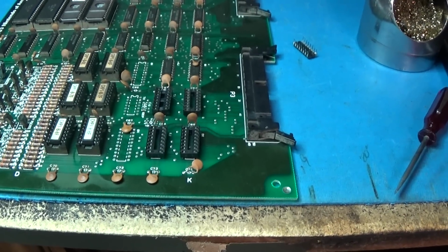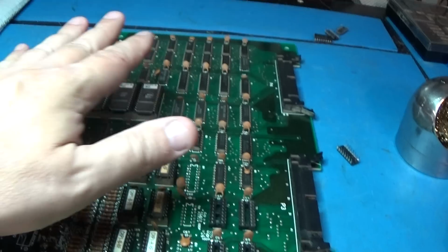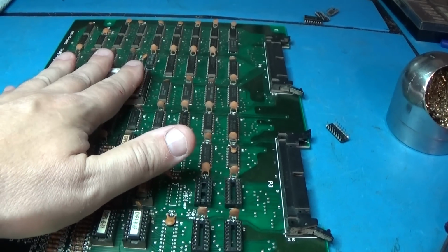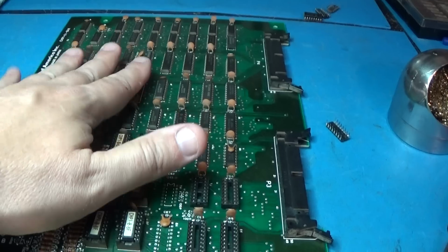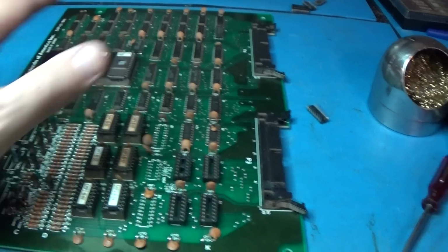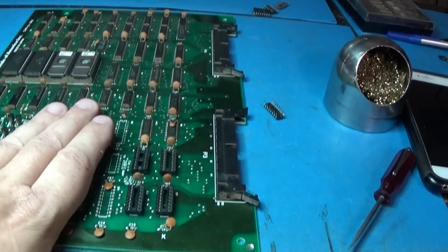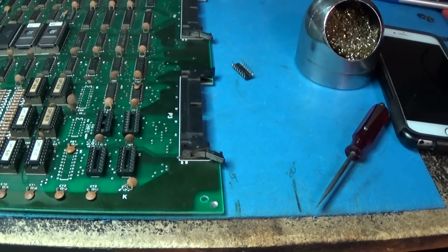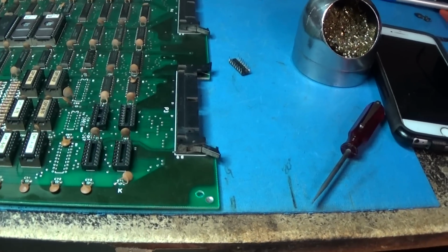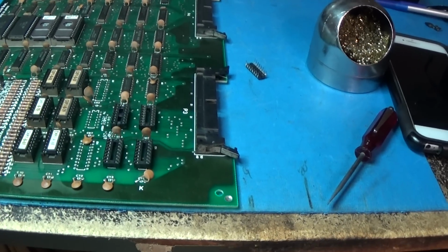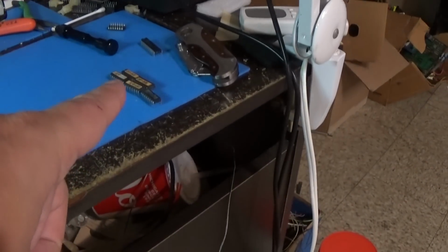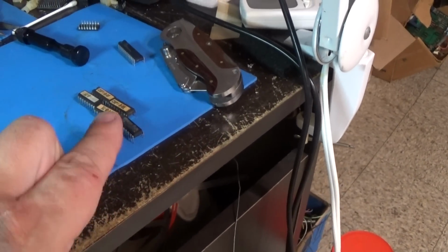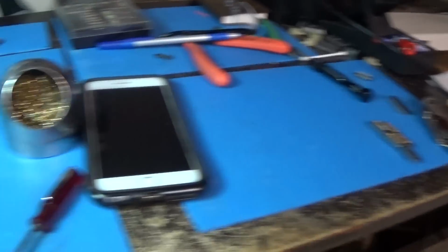But I'm going to go ahead and pull and verify all of the software in this board set. All of the video ROMs, I'm going to verify them all to Punch-Out. And I'm putting in 353s, which I do not have any of, so I have to order them. And then we'll pick back up with this one after I get these 353s, and hopefully that fixes this. Because I don't know what to do with these guys. I don't know what the data is supposed to be. I mean, all six of them are bad. That's kind of fishy. So I really don't know.